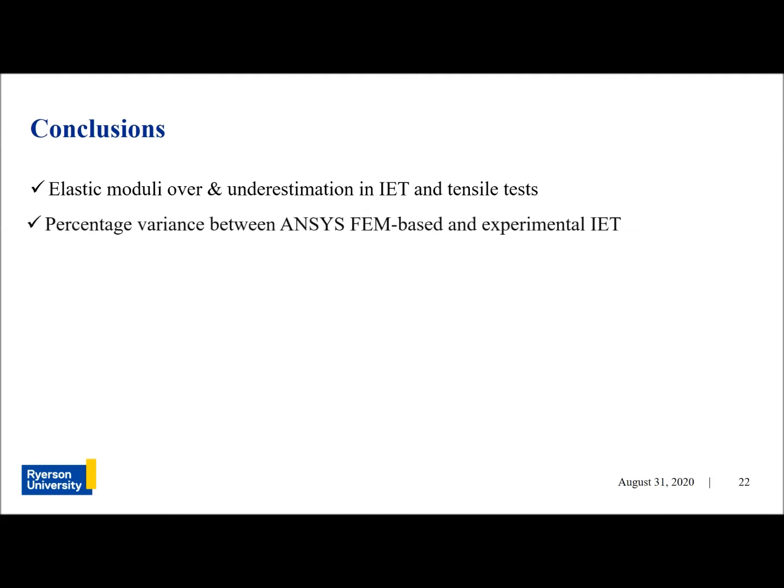By comparing fundamental flexural frequencies obtained through both ANSYS FEM-based simulations and experimental IET, the average variances are found to be between 0.41% for XYZ and 2.1% for XZY build directions. The overall average variance is found to be very small, less than 1%.